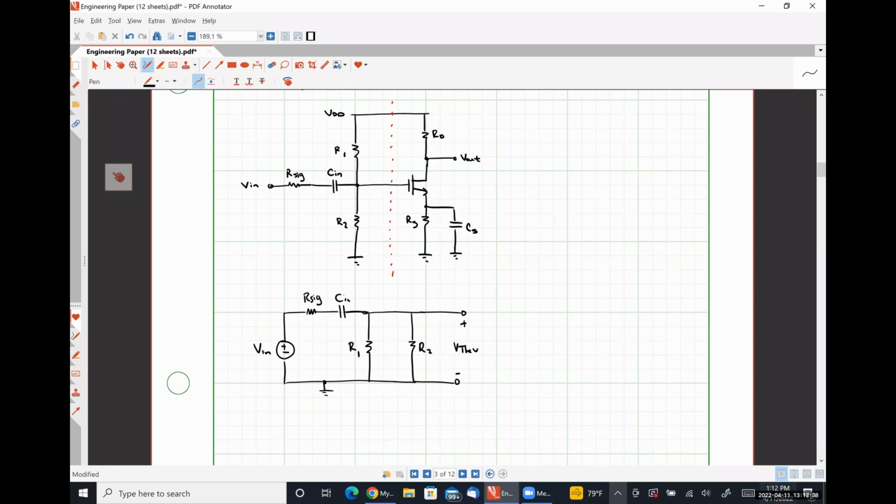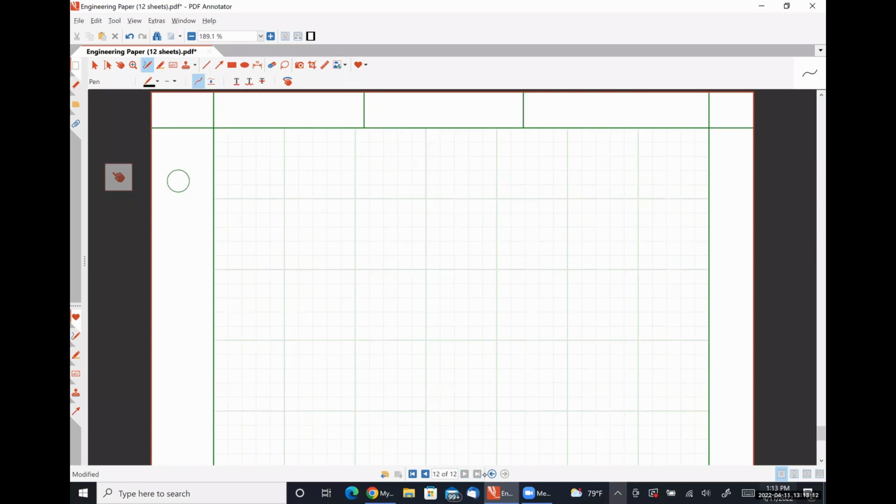Why doesn't the capacitor go away? It doesn't in the other stuff we were doing. So fantastic question. The reason why the capacitor doesn't go away is because we're specifically working at a frequency where it's not a short circuit anymore. If it were a short circuit, we would no longer have a frequency dependence, right? So I don't want you guys to write this down, but I want to be very clear about what we're doing here, okay?